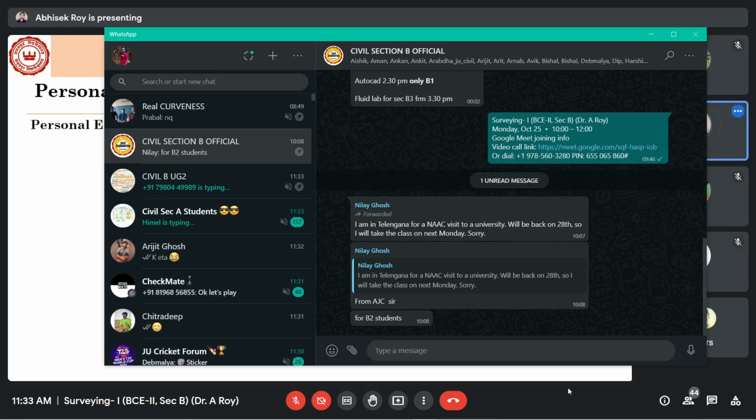So what will happen? You can see that your object is properly bisected, but that small amount of measurement will not be there in the scale, because you have done it with the help of the lower tangent screw, or I should say the bottom tangent screw. So no measurements will be there.